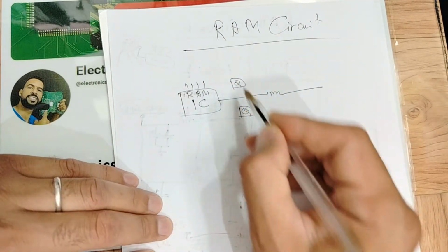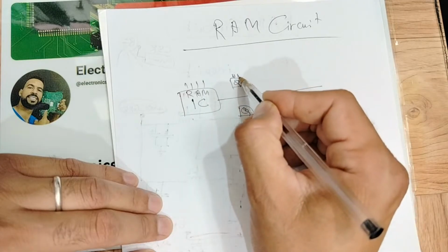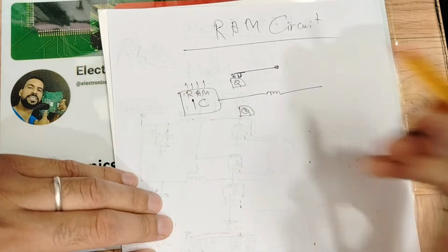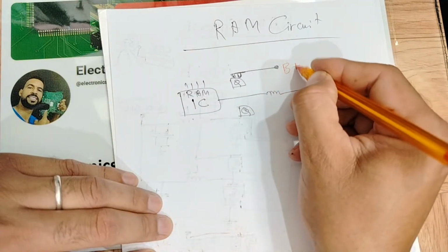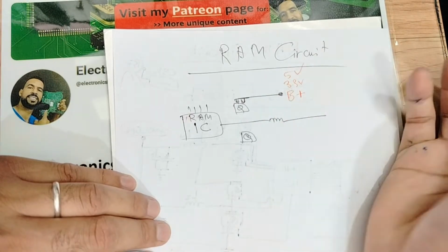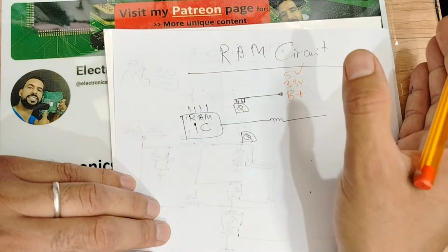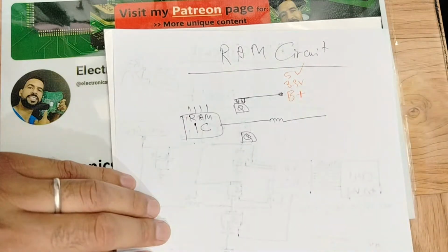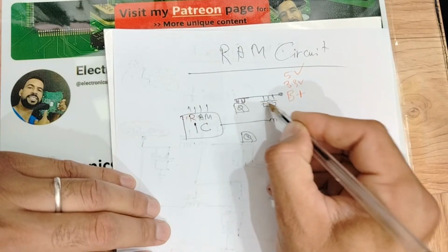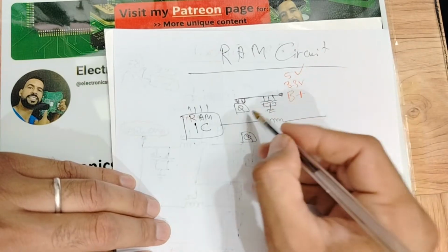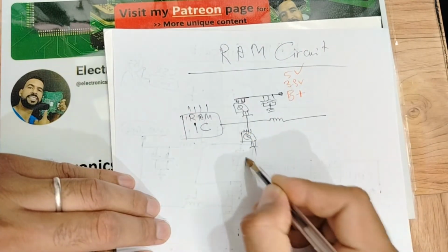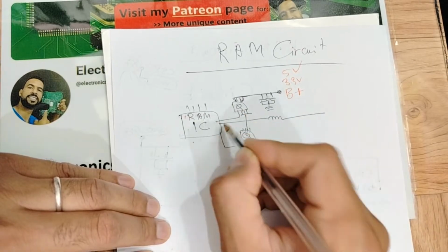Okay, the same working principle. This MOSFET will be connected to what? It will be connected to B plus, sometimes to 3.3 volt, and sometimes to 5 volt, depending on the type of the laptop. Okay, my friends? Of course, here always we have ceramic capacitors connected to ground in the input, the source connected to the drain, the source connected to the ground. Here controlled by the IC.